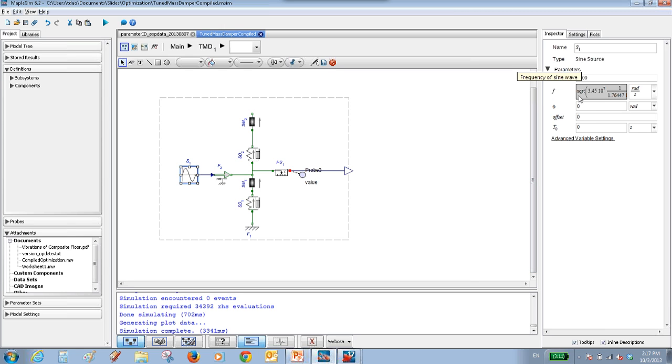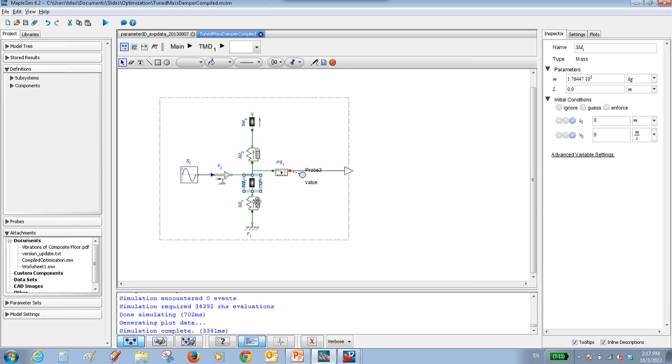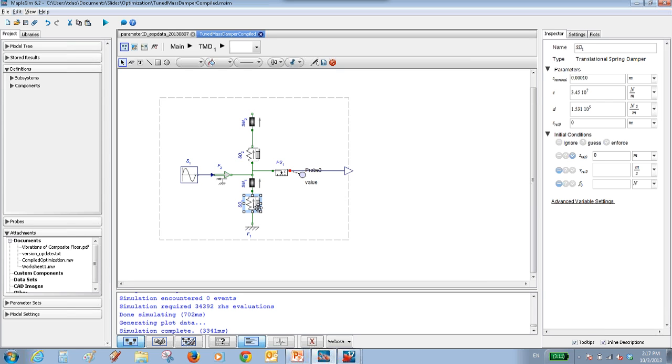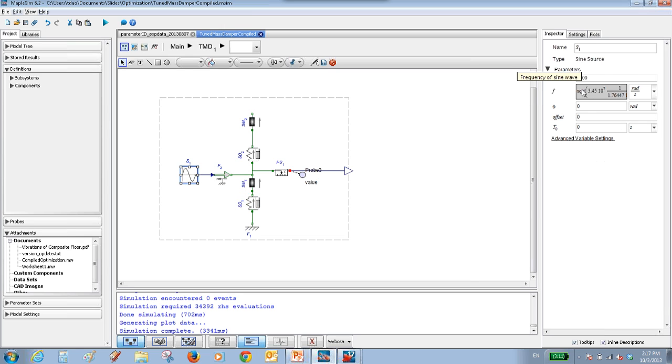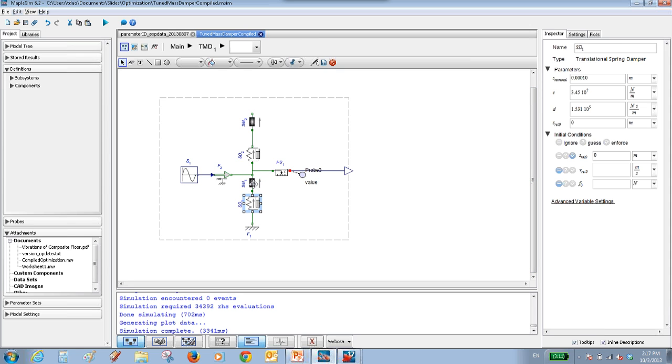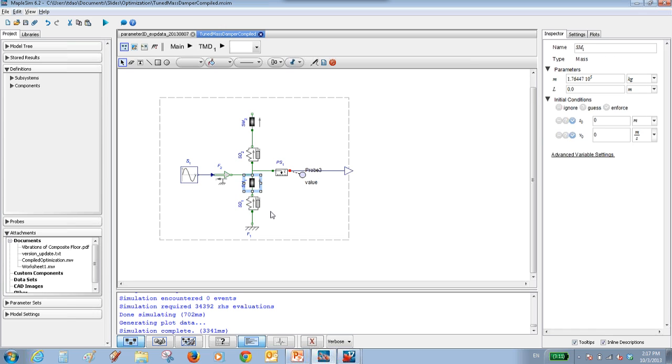The most important parameter for the excitation force is the frequency of the vibration, which is calculated based on the mass and the stiffness of the cantilever beam. The frequency is equal to the natural frequency of the system of the dance floor combined with the springs and damper.